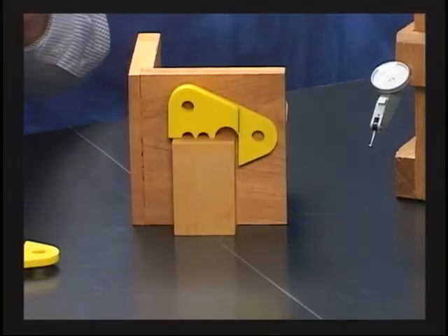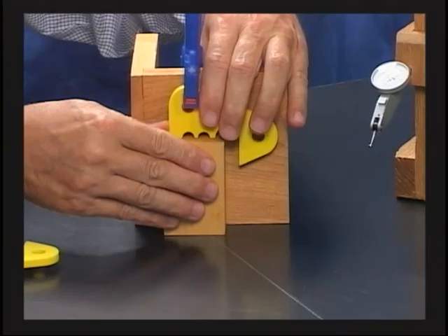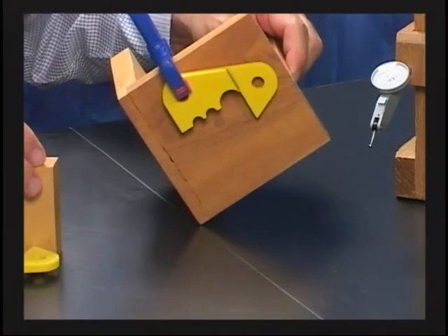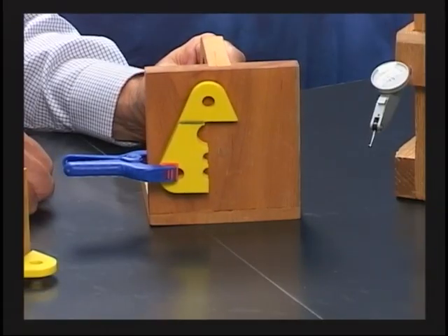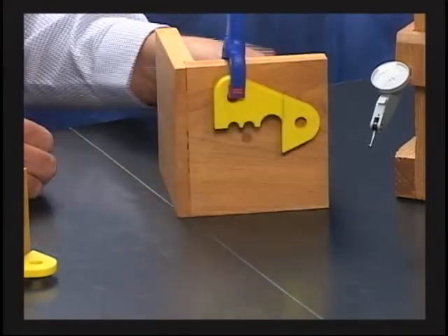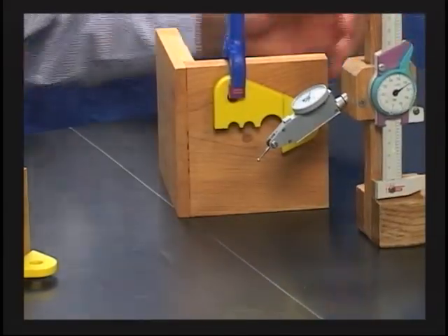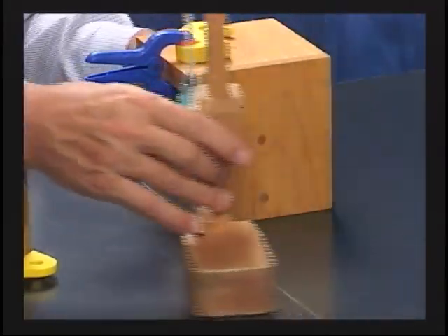And the reason I'll raise it up a little bit is so I can get a clamp on. And that's now lined up to my primary datum. Now once the part is lined up to my secondary datum, you notice when I'm going to make any measurements on here, that would be pretty straightforward. Making any measurements in this direction, you see I just take my height gauge. Well, first of all, I guess up and down, I could take all my measurements in this direction.